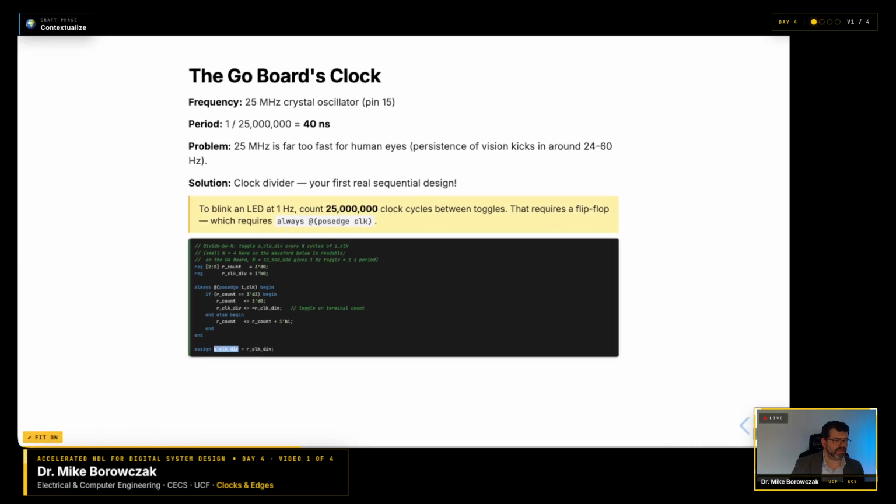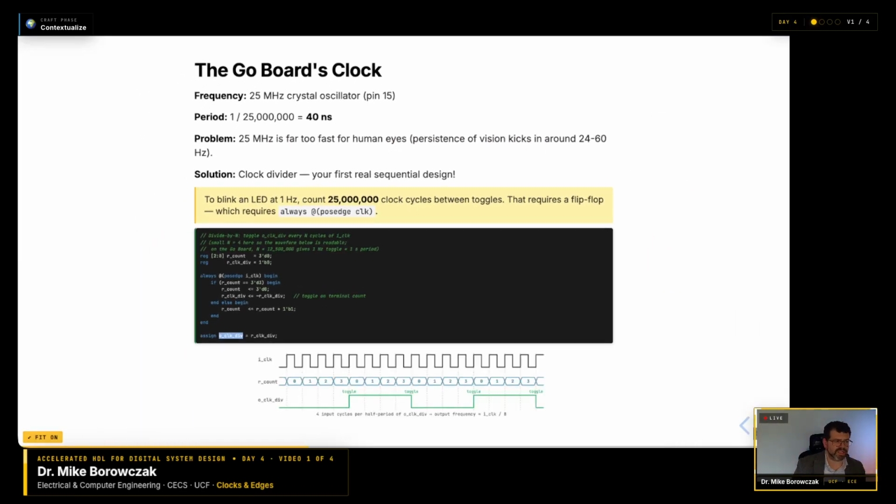So what does this look like? We have our input clock here running at some frequency, and we're going to start counting. We count at the positive edge of this clock here, iClock, and we get 0. That's where it starts. So imagine that we just start at 0, and at every subsequent positive edge, we are incrementing by 1. So you see 0, 1, 2, 3.